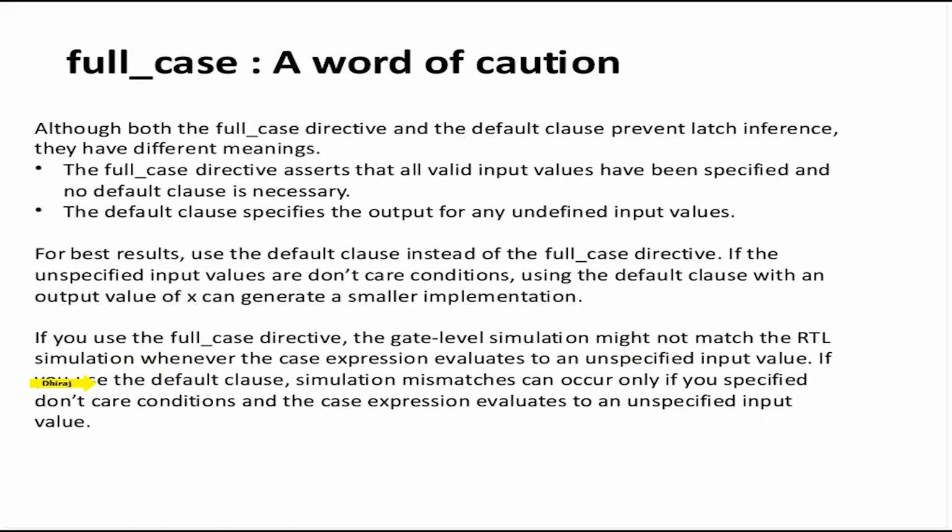If you use a default case, simulation mismatch can only occur if you specify a don't care condition in the case expression. So in the first case, when you use full case and your simulation mismatch occurs, it is difficult to debug. But in the second case, since you set the output value to X, it is easier to debug. So it is always preferable to use a default clause and not use full case.